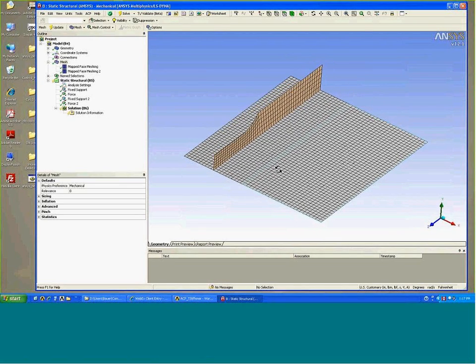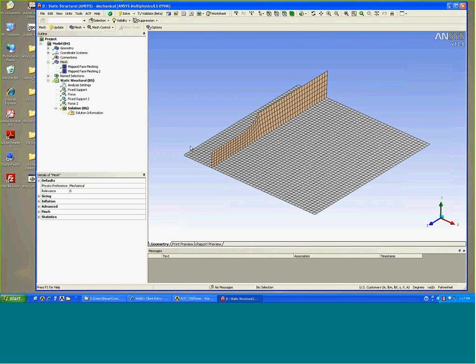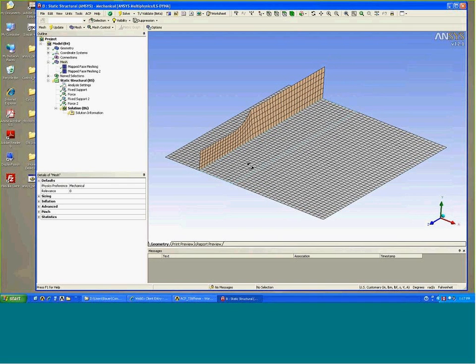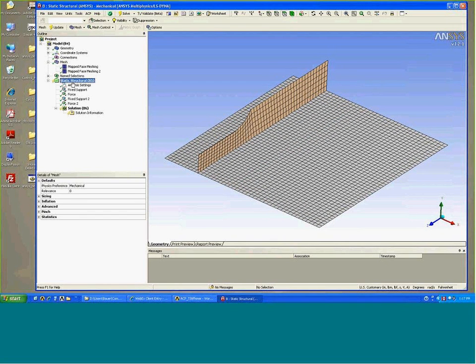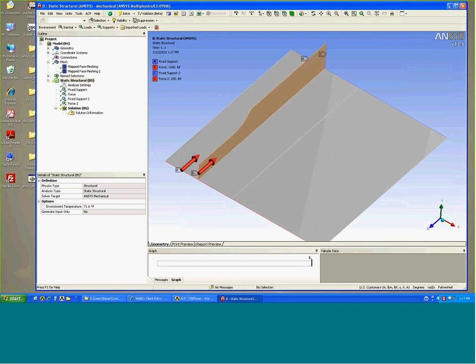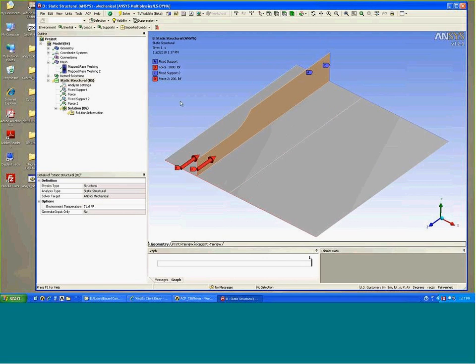In this case here, I've set up the model with an example mesh, and these are shell elements, and we'll go through this example with shell elements. As we can see here from our static structural folder, we have applied loads and a fixed boundary condition. From within Mechanical, if you highlight the static structural folder, you can go up to the top menu and launch ACP from within Mechanical. ACP can also be operated from a standalone procedure and essentially working with ANSYS Mechanical APDL CDB files or archive files.